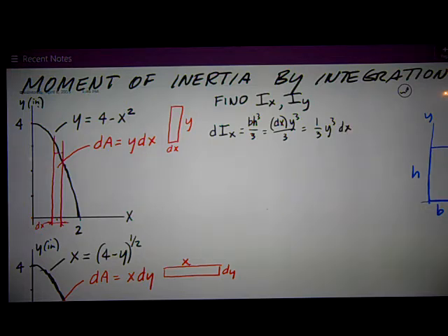So to get the moment of inertia Ix, we're going to integrate that instead of what's on the equation sheet. Ix is equal to the integral of dIx, and we just said that that's the integral of 1/3 y cubed dx.